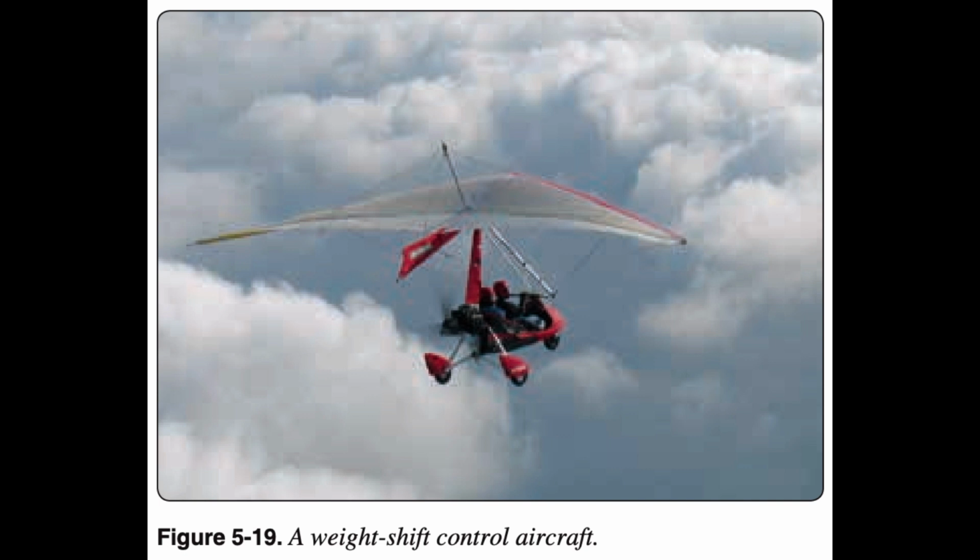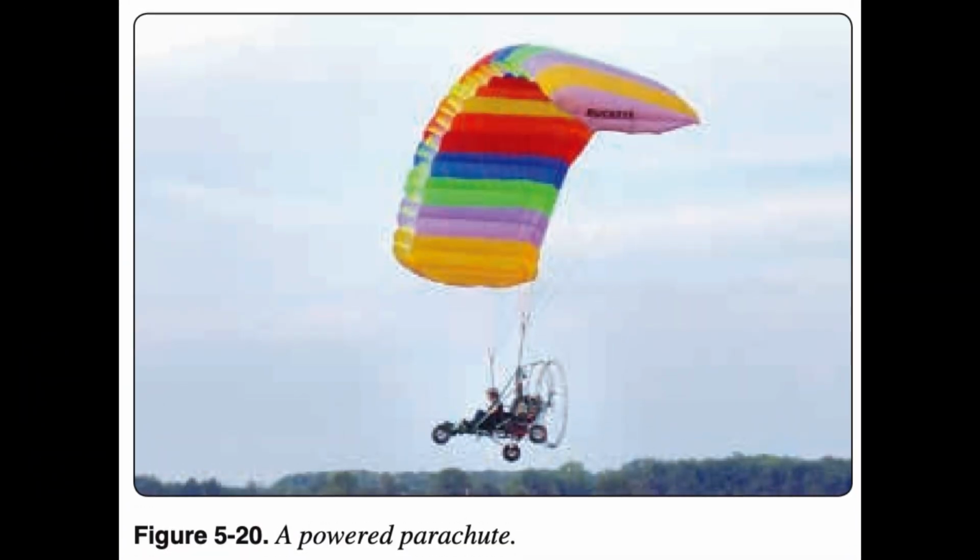In the case of powered parachutes, aircraft control is accomplished by altering the airfoil via steering lines. A powered parachute wing is a parachute that has a cambered upper surface and a flatter under surface. The two surfaces are separated by ribs that act as cells, which open to the airflow at the leading edge and have internal ports to allow lateral airflow. The principle at work holds that the cell pressure is greater than the outside pressure, thereby forming a wing that maintains its airfoil shape in flight.